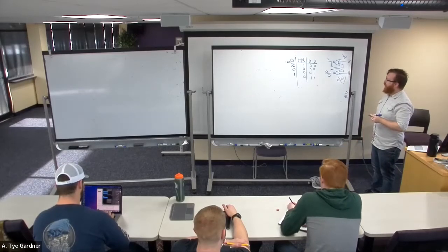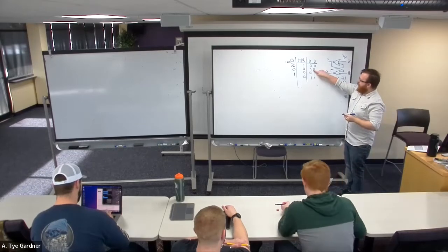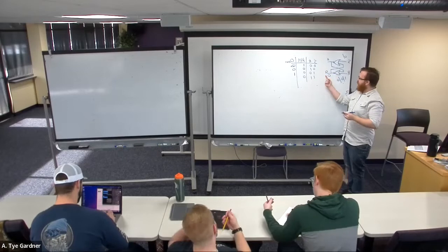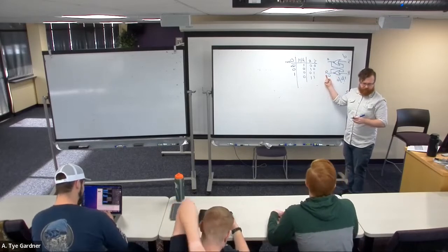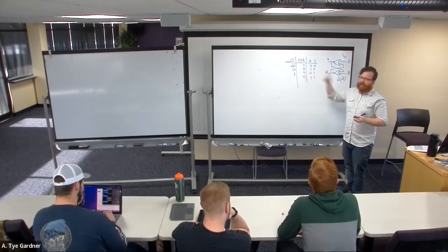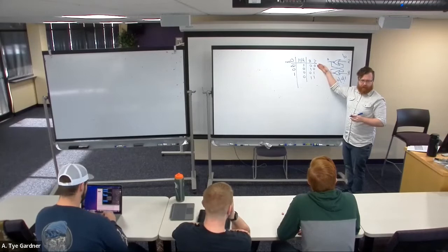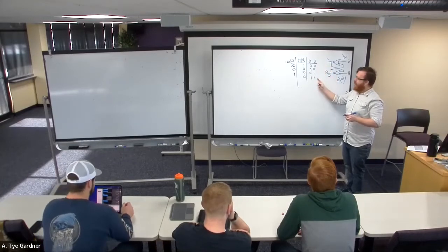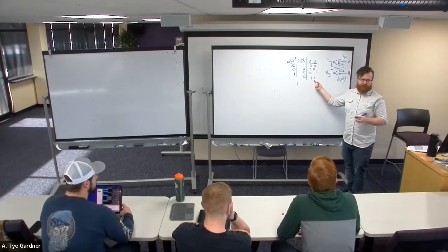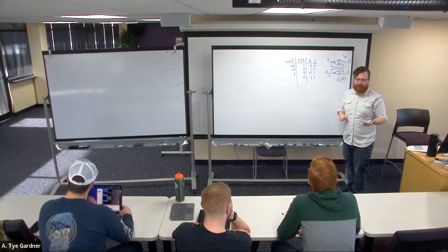There is, however, a bit of a problem. We can now say that R is reset, which is to take the Q output and tell it to be 0, reset to 0. S is set, it makes the output 1. If I neither set nor reset, I remember. What happens if I am attempting to tell a signal to be both 0 and 1? It's problematic, right? It's not really going to work.